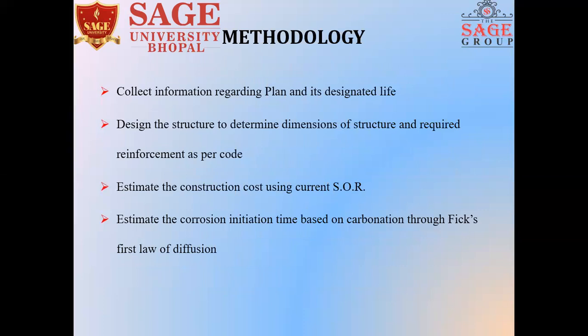Then what is the methodology? First is to collect the information regarding the plan and its designated life, then to design the structure, to determine the dimensions of structural components and required reinforcement as per the code of practices. Then to estimate the construction cost using the current SOR. SOR means schedule of rates.